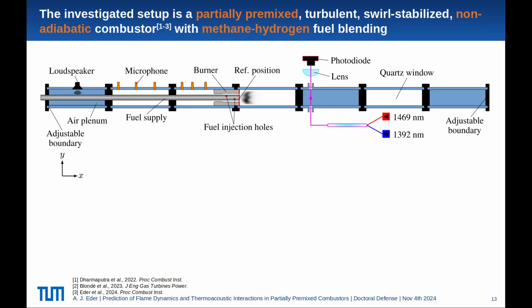And we want to investigate the entropy response of a partially premixed rig with real experimental data, which we can use for validation of our numerical approach. And therefore we collaborated with ETH Zurich, and this is the rig under investigation. So it's a test rig under ambient pressure. We have again loudspeakers to force the mass flow, microphones, we have a burner, and we have a two-staged fuel injection.